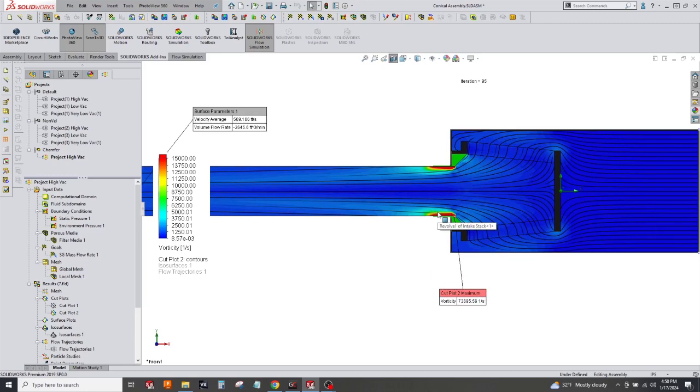transition into a tube or out of, this also applies to coming out of a tube. This is never a bad thing if you have the capability, the room, and the just overall ability to do it. If you're not trying to pinch and get every last little bit out of it, let's look at those velocities, and if we're around that 100 feet per second, then maybe it's something really worth pursuing. So I hope that was useful. A lot of fun doing this, kind of informative. I'm really surprised about the chamfer.